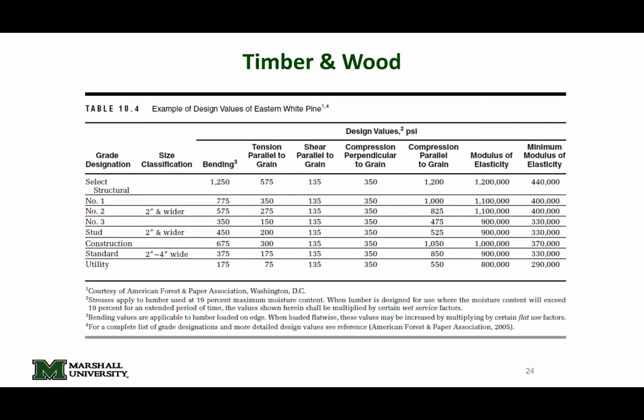The other thing that will definitely become the star of the show next semester are the adjustment factors, okay? I'll give a highlight on this in a little bit, but what we're looking up here are what are called reference design values. We do not use reference design values at the end of the day when we're doing timber design. We use adjusted design values. So these values that we look up are ideal world conditions, and what we have to do is take these values and adjust them to real world conditions. And unfortunately, we have to adjust them quite a bit.